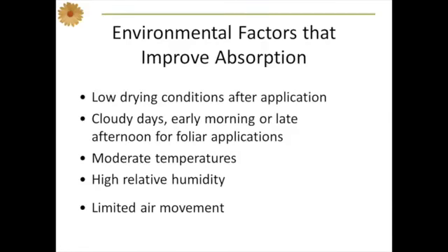Right, drying conditions. Brian mentioned this a little bit earlier as well. If we want to improve absorption, we want to look at conditions that allow for very slow drying after application. Cloudy days, early morning, late afternoon, moderate temperatures, high relative humidity, and limited air movement.